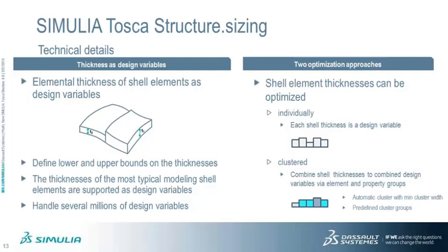Now the good thing here, the absolutely fascinating stuff, is that you can use both approaches independent of the fact that in one case you have relatively fewer design variables, maybe 10 or 100, and in the other you have millions. Still you don't have much more computational effort. This is because we are using the sensitivity method, computing the adjoint sensitivities, and this does not bring more computational effort in the method.